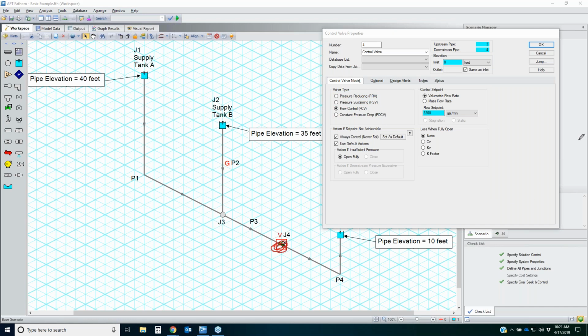So what you might have is feedback somewhere else in your system where you might be getting information in any of these particular pipes, and that's what you can use to do remote sensing. So if you use the goal seeking control module, you can change your set point for any of these parameters automatically in order to meet your goals and variables for pressure or flow or temperature or velocity in other areas of your system.